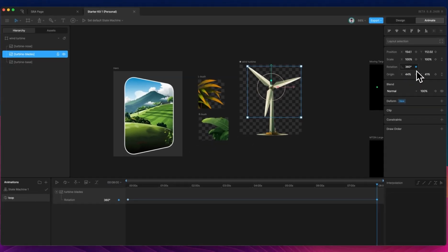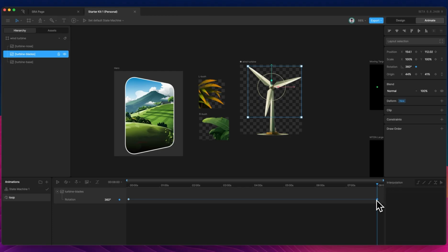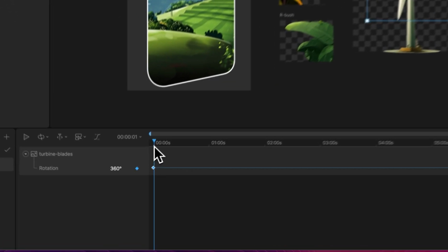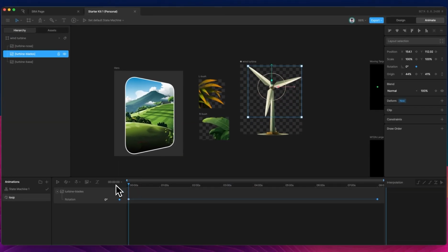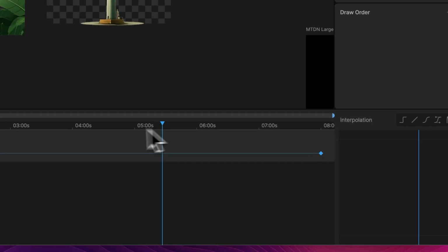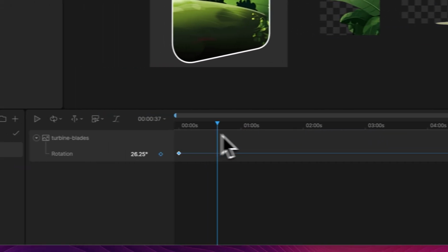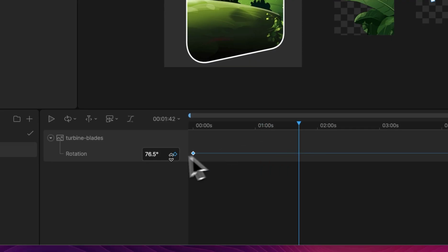And you see once I hit enter, this lights up, which means that there's a keyframe here. So if you look at between the two, nothing much has changed. But because it's set, everything in between is going to go from 0 seconds to 360 by 8 seconds. And it's called tweening. Everything in between, it's going to automatically just set the different rotations between the two.